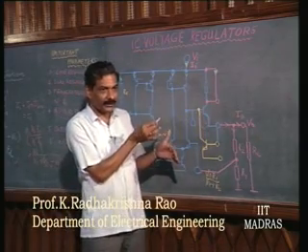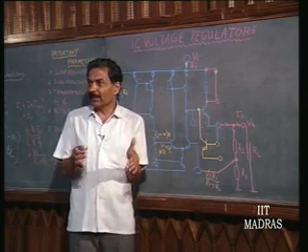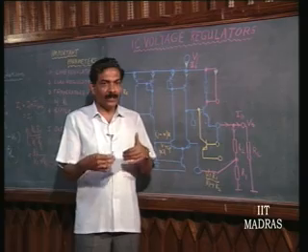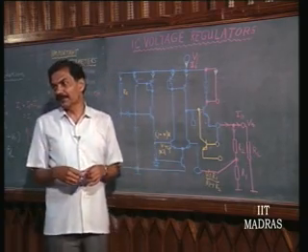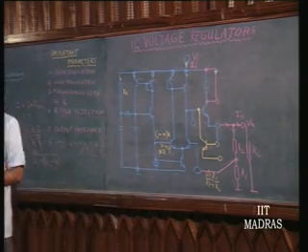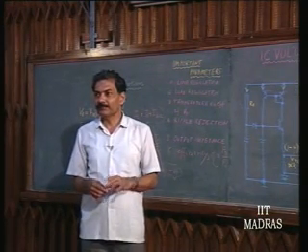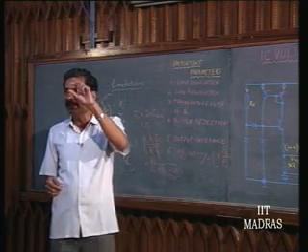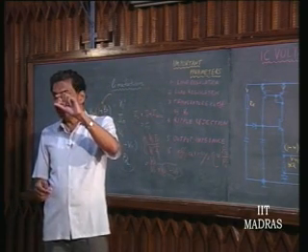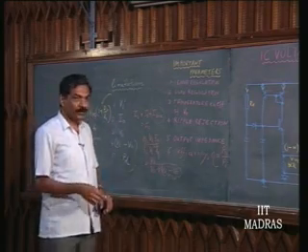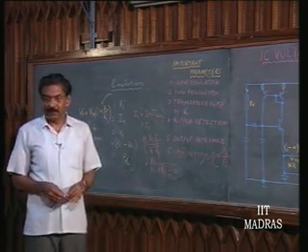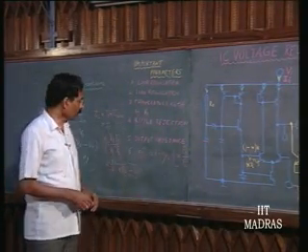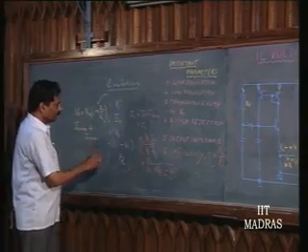You can quickly look at the circuit, or 723, you can quickly look at the circuit and for yourself find out what will be the V naught minus Vi minimum that can be had in a given circuit. Have you understood this? Is it clear? So, collector to base voltage, the limitation is that it can be made as small as 0 volts. Given that, the rest of it is due to the V gammas. In this circuit, it is 2 V gamma. Okay. So, that is one limitation.